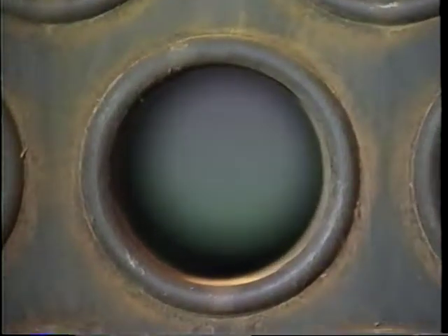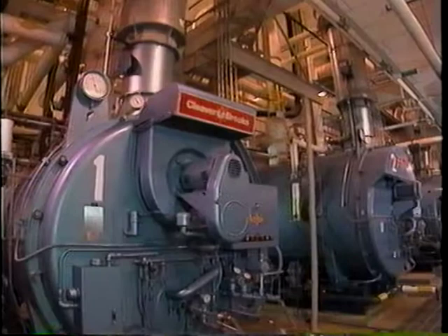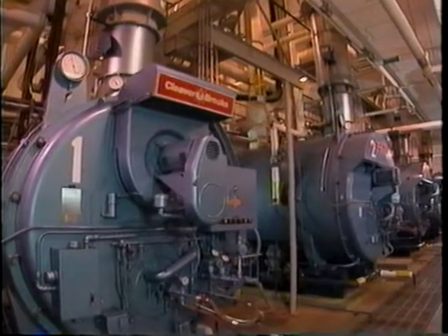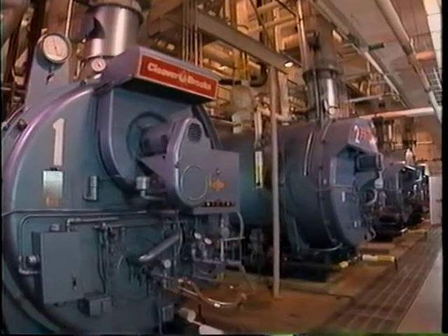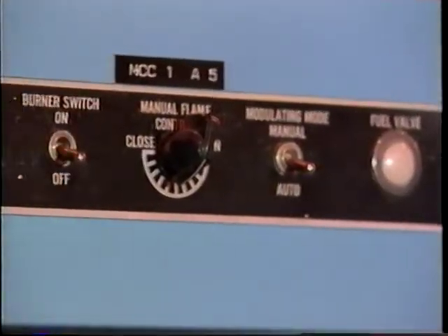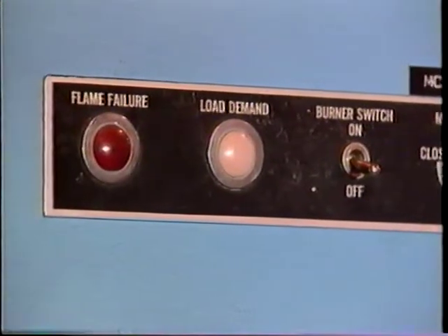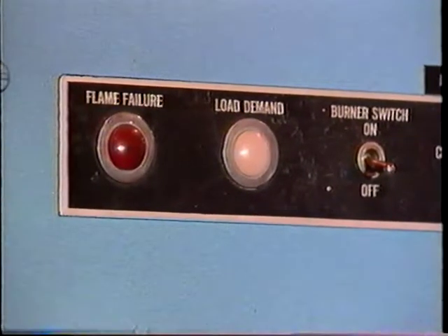Tubes in a fire tube boiler are measured by the diameter of the tube in contact with water in the boiler, or outside diameter. Fire tube boilers are high or low pressure boilers and contain a large amount of water. Because of their vessel size, fire tube boilers can respond to load changes with minimum variation in steam pressure.